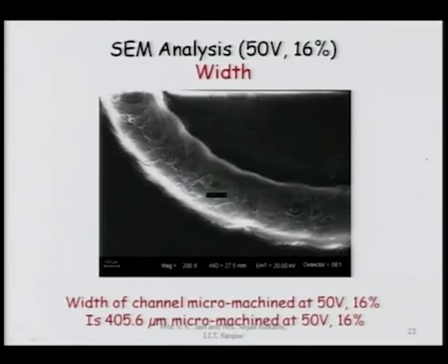Now, this is a thermal process, and you can see a lot of cracks formed on the machined surface, and these kinds of cracks are not acceptable in a real-life product. So, one has to optimize the parameters so that the cracks etc. are eliminated during formation of the channel, groove or hole.